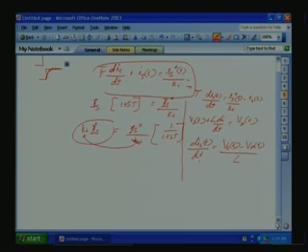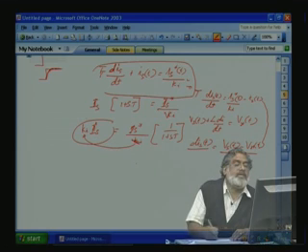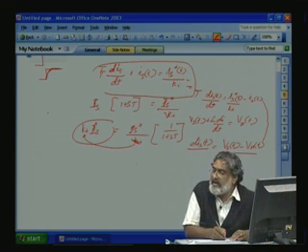So, equating these two equations, this one with respect to this one: this equation is what is actually happening in the converter. VRT is the actual VRT, but what we want is the VRT star for a first order response. So, let us equate these two equations, introducing VRT star.